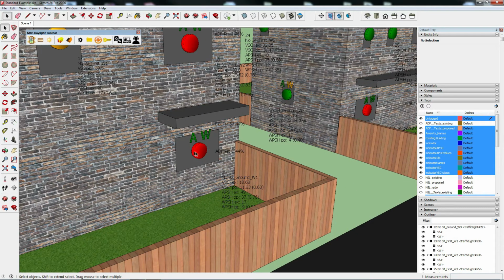Okay, so each traffic light marker is split into three areas. We have the circular shaped lozenge. This indicates the VSC value. So it's either going to be green, orange or red, depending on whether it's passing or failing. Orange indicates within 1% of a pass, but still failing. So here we obviously have a failure for VSC.